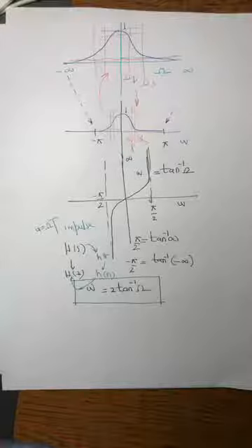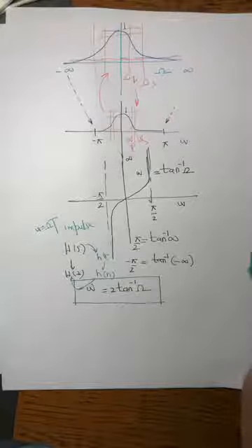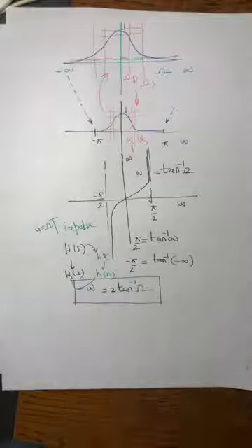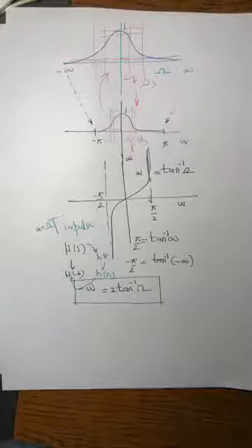Does that mean that we are representing infinite frequency with pi in digital? Yes, we are basically representing infinite frequency by pi. But please remember that this is all theoretical. It means you are not actually designing an analog filter using capacitors, inductors, resistors. You're just mathematically using the techniques. In that technique, you want to bring that infinity back to pi, so that the specifications you have there, you meet those specifications, and still you have an analog filter.